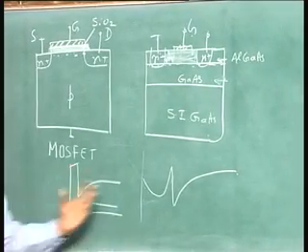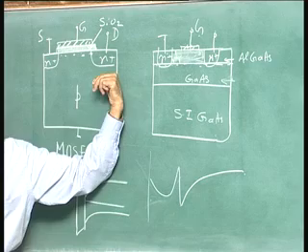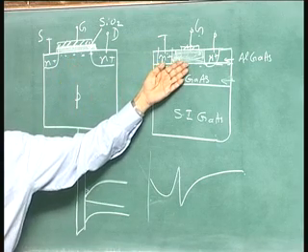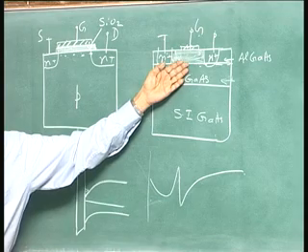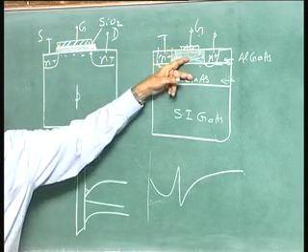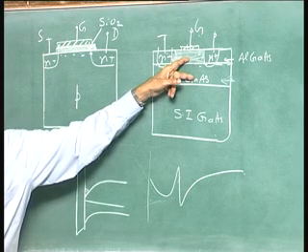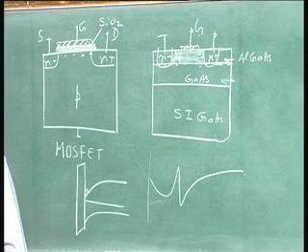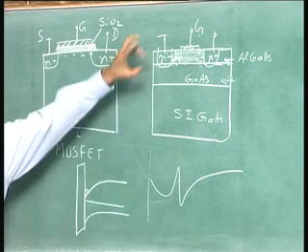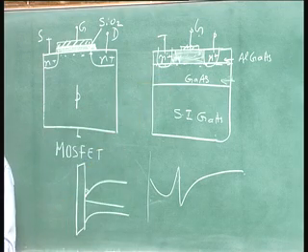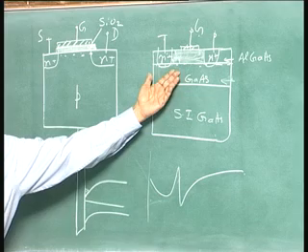So, between the two insulating layers here, this has epsilon r equal to 4, this has epsilon r equal to about 12, 12.8. So, for the same thickness, this will have larger capacitance, which would mean that the coupling between the gate and the channel will be better. Okay. For a given voltage change here, the charge that will be here will be more. Q is equal to C into V. For a given V, if C is large, Q is large. That is what is happening here.